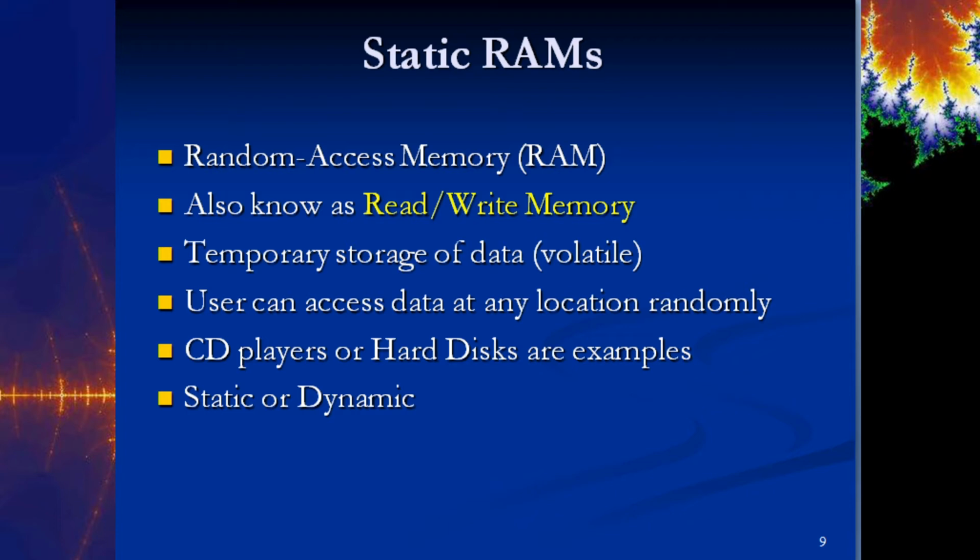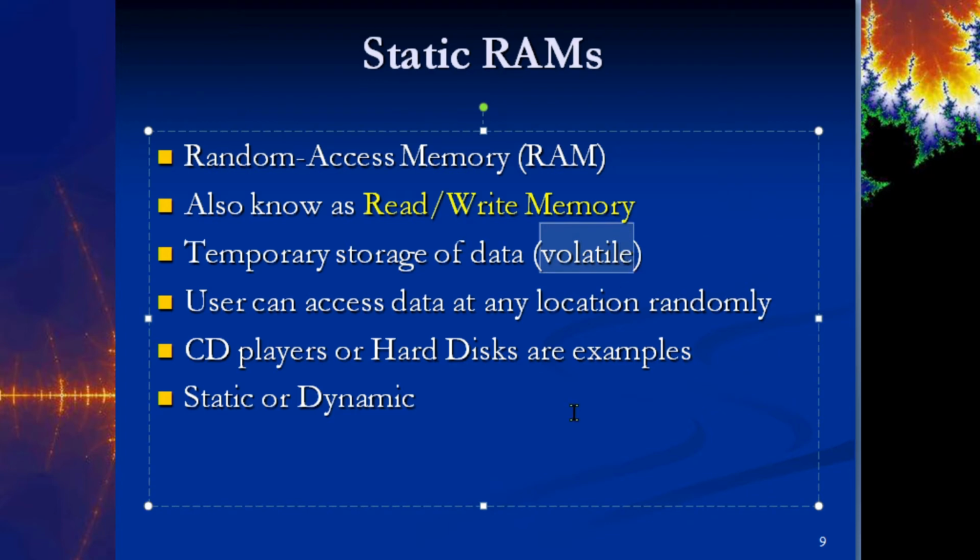And as usual, when we talk about RAM, we're always talking about volatile memory. Okay, in other words, if you remove the power, you lose the information. So the Altera boards, the DE10, the DE1s, unless you buy a certain type of proto board, all of the Altera boards that we use are volatile. You have to download to it every time you connect it.